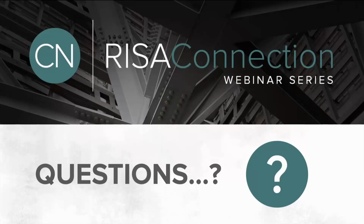Let's see, we have a few questions here. One asked about the round tripping, the integration with RISA 3D again. After we extract a model from RISA 3D, or detach, I think was the question, we've basically broken that link with RISA 3D, so we can't send it back to RISA 3D at that point. That essentially breaks the link, and it allows us to fully play with the loads and the different pieces of the model. That's why we lost our groups in that case, because we're no longer tied to that RISA 3D model.